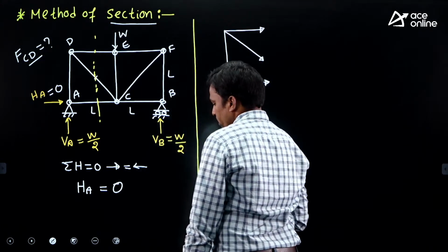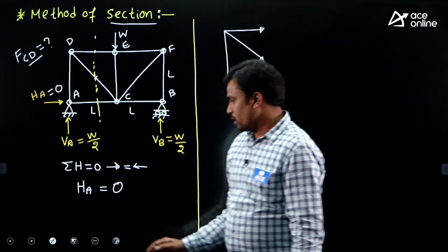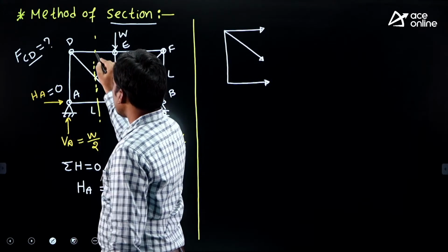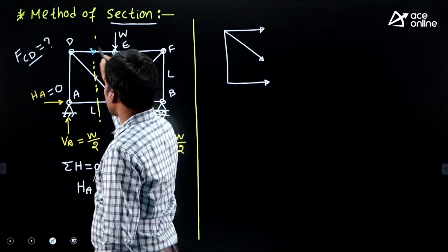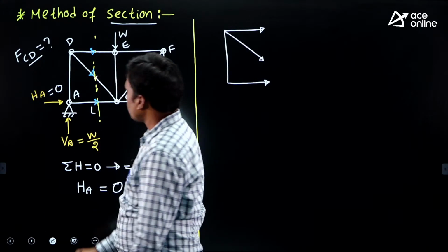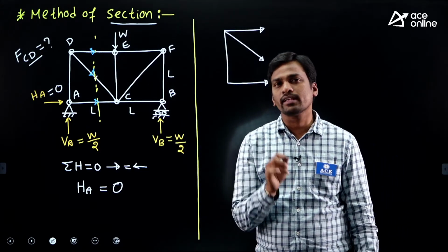Students, we are doing the analysis for the left part of the structure now. Then only for the left part cut members, initially assume tensile force.